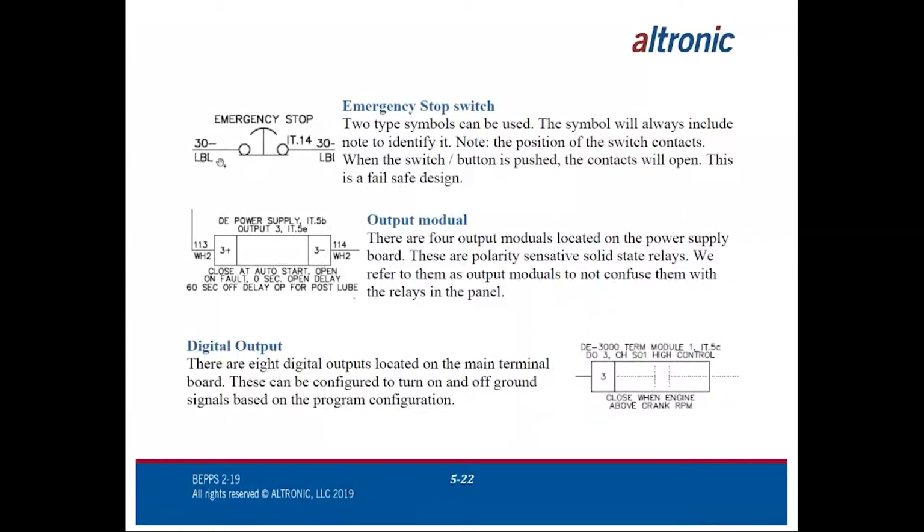So everybody see that? So the wires come into each side of it. They need to be connected, but when the operator pushes that switch down, some people call that a mushroom head or something like that, these contacts will go up. Now, I have seen mistakes in drawings before where this contact is actually drawn on top, but this is the proper way. Sometimes too, there'll be a little arrow under this that might reference other pages, other locations, because the same ESD button could have multiple contact blocks on it, so just be aware of that.